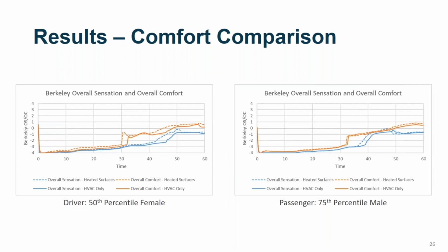How do you change the preconditioning environment for the humans? In this CoTherm process, there are a couple of key properties that correspond to a preconditioning temperature and a preconditioning relative humidity. That sets your preconditioning environment. In this case, I set it to 20 degrees C and I think 45% relative humidity. But those are just a couple of key properties in this process that you can change to alter your preconditioning.